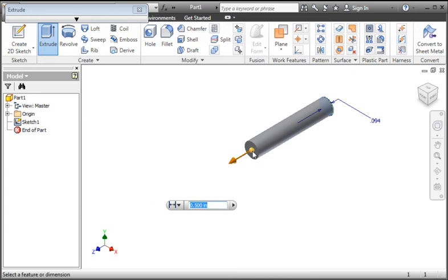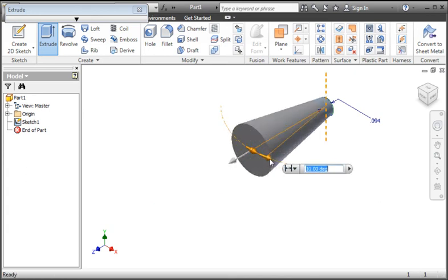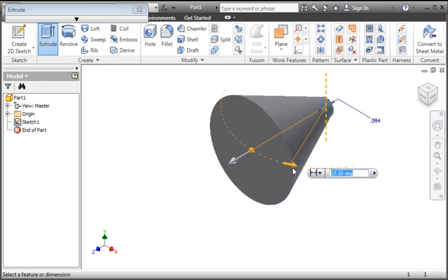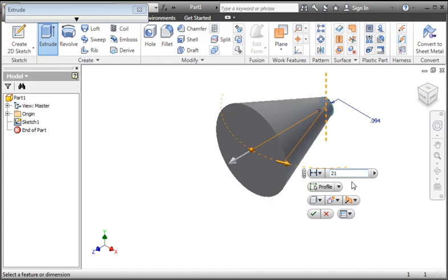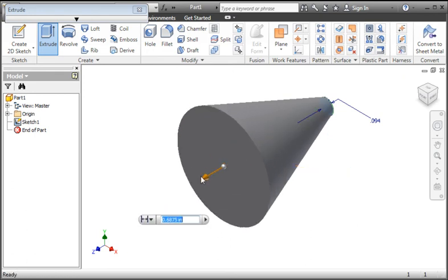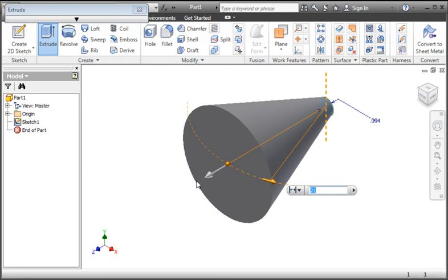You can also drag the sphere to change the draft angle. This adjustment snaps every 5 degrees. Anytime you're dragging a manipulator, you can stop dragging it and type a value to precisely set it. So the fastest way to use these settings is to start the drag and then type the value. You can also type the Tab key to toggle between the linear dimension and the angular dimension.